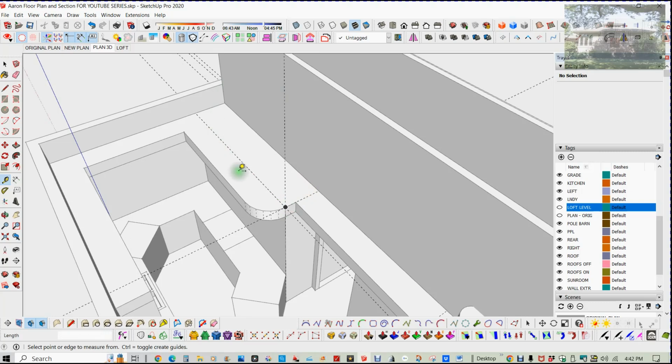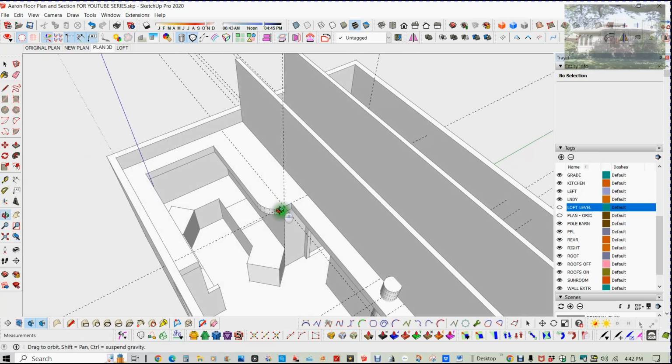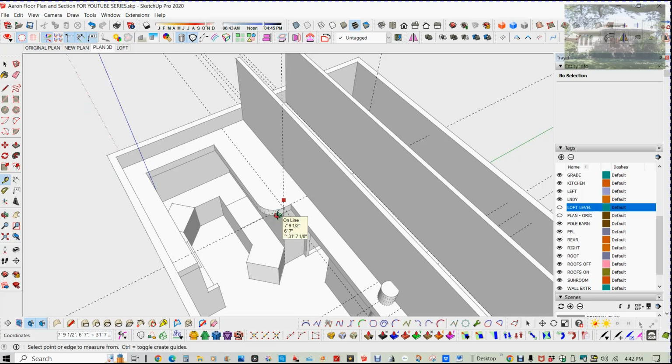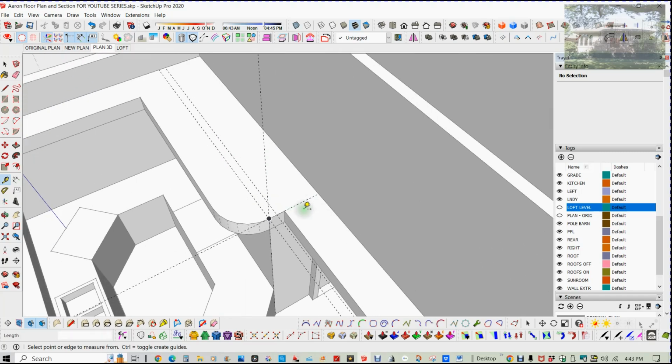I want to make more space up here for the utilities. This building's got a slab on grade, and plus there's hardly any space on the first floor for a furnace or a boiler. It's just difficult to run ductwork in concrete. So we're putting everything up overhead, not to take up any extra space and to avoid spending extra money on something that probably isn't really necessary.